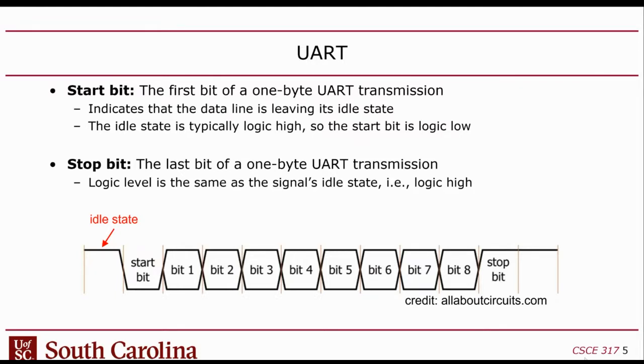But before you send a word, you put out a start bit, which just means that the driving side, the transmitting side, pulls the voltage down to ground for 1 bit time. Whatever the bit rate of the channel is, I should say the baud rate, the reciprocal of that gives you the time. So if it's 9600 baud, then it's 1 divided by 9600 seconds. That's how long you pull it down. That indicates that you're starting.